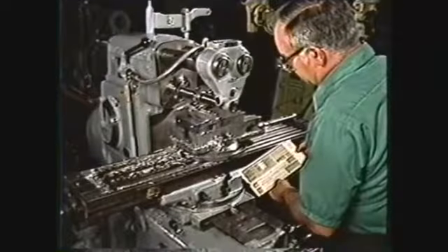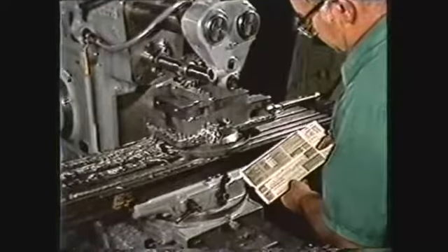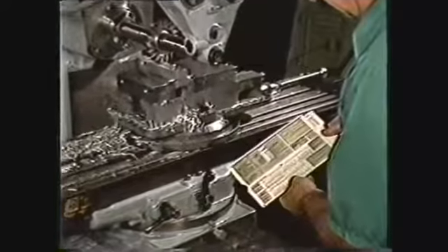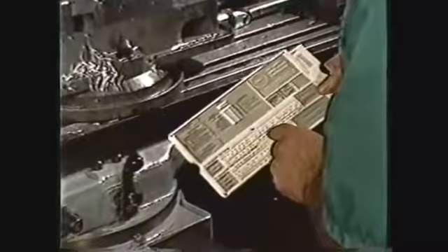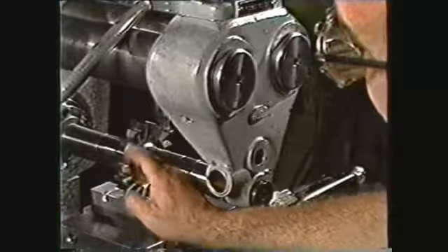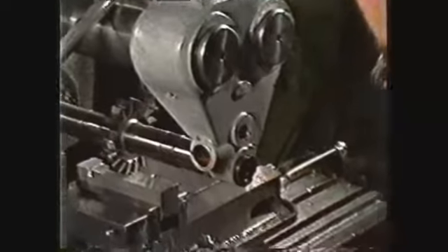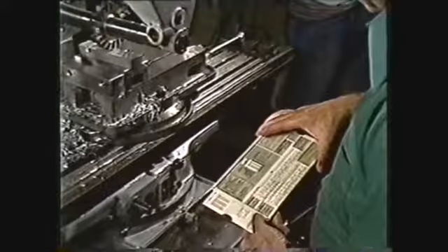The cutting foot speed of the metal is 500. By knowing the diameter of the cutter and using the speeds and feeds calculator, the spindle RPM can be determined. Determine the feed rate in inches per minute by counting the number of teeth on the cutter and matching this up with the spindle RPM on the speeds and feeds calculator.